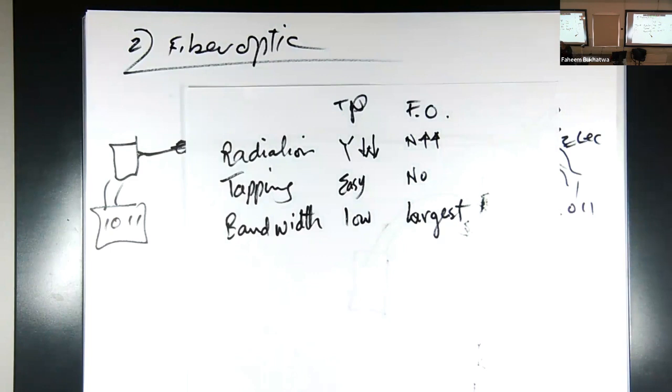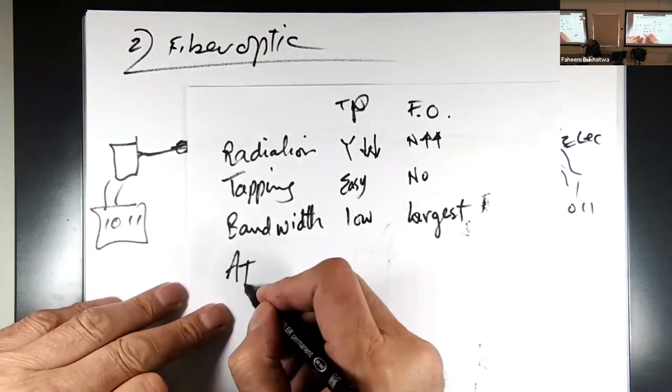Every few years, somebody comes up with a better switch that can fluctuate light in different frequencies, and they try it on fiber optic and it works. So far there's still a limitation of the switches that generate the frequencies, rather than the fiber optic. So possibly right now, one fiber optic wire can carry as much as 1,000 twisted pair wires can carry for one single wire. So that's the approximate range, if we compare the 2 of them. What's left is attenuation.